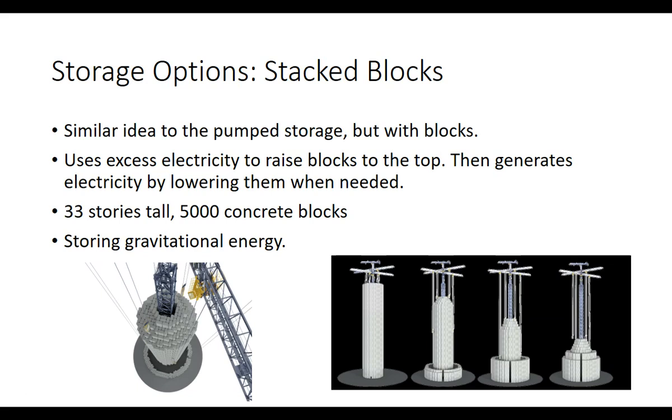One that I don't think we're using at all, it's just one of these things that people are talking about right now, is basically the same idea as pump storage, but you're using blocks and cranes. When you have extra electricity, they're raising these really heavy concrete blocks and stacking them on top of this pile here. And then when you need the energy, you lower the blocks back down to the bottom and you generate electricity by lowering these heavy concrete blocks. So it's just like pump storage, you're basically storing gravitational energy, but instead of doing it with water, you're doing it with these concrete blocks.